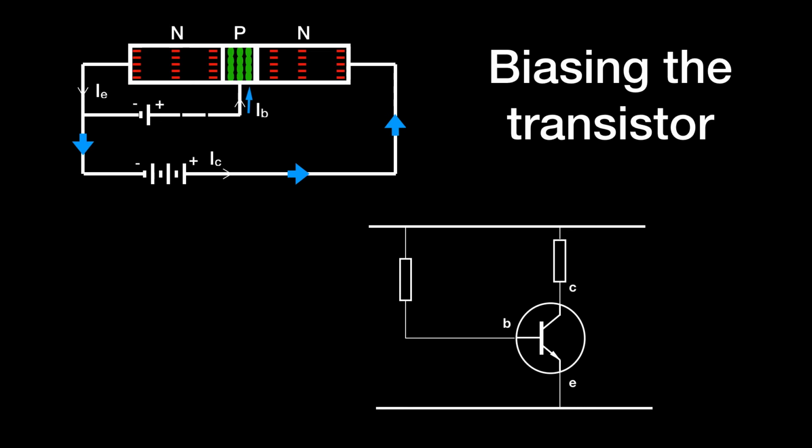Transistor connected, in this case between a positive and a zero rail, and a resistor in the collector circuit to limit the overall current going through the transistor so it's not damaged, and similarly a resistor connecting the base to the positive rail in order to forward bias the transistor.